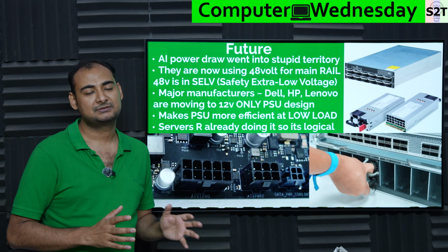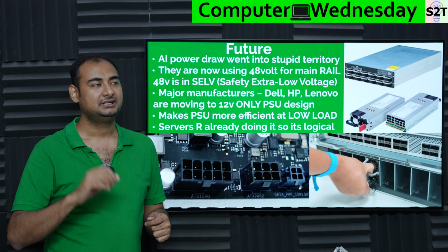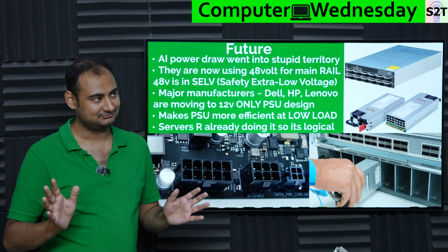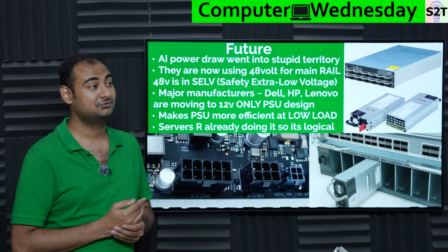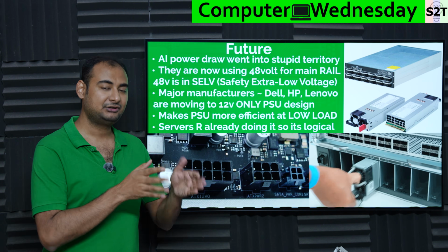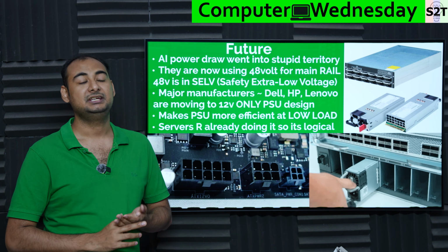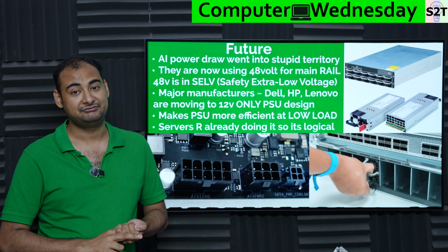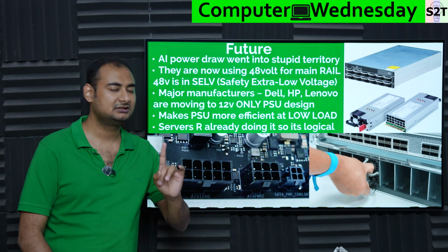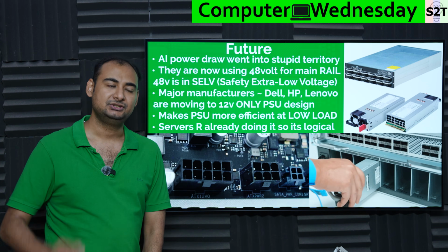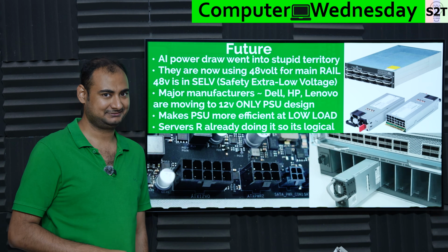Meaning, right now power supplies are rated for 80%. That's why that 80% platinum, that's the whole point. At 80% load, it should be this much efficient. Okay, cool. But what if you want more? What if you want at low loads? If you have multiple voltage rail, like you have 3.3 volt, 5 volt and 12 volt, it's very brutal to design a power supply that can be efficient. Physics will not allow you to, like, no. But if you have single power rail, 12 volt the end, you can allow the power loading to go down very low and still be efficient.